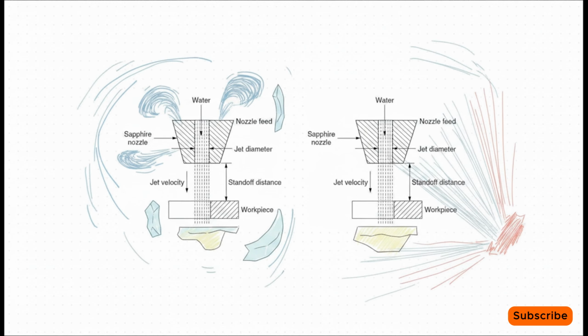But the key here is the standoff distance. That's the critical gap between the nozzle and the workpiece. As the water jet exits, it inherently diverges. It kind of spreads out. The wider that gap is, the more of that precious kinetic energy is literally lost to the air before it